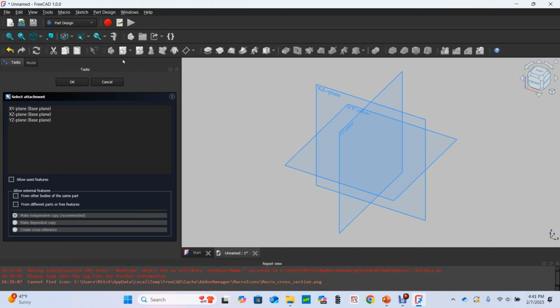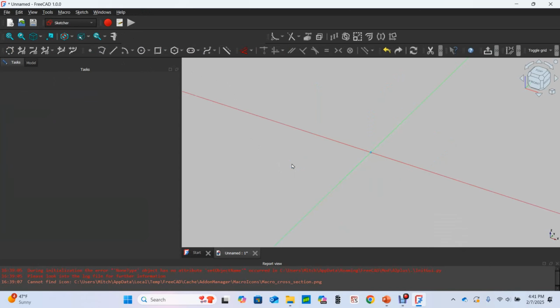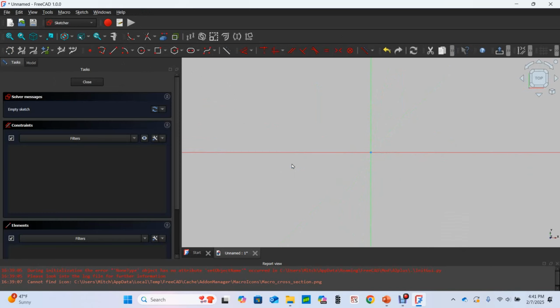And in Sketcher, if you want to make things easy on yourself, choose the top of the XY plane for your sketch. CAM automatically assumes that the tool is coming from the Z plane. You can change that, but it adds one more step. So sketch and pad your part just like you normally would, and I might fast forward this because it's not the point of the video.